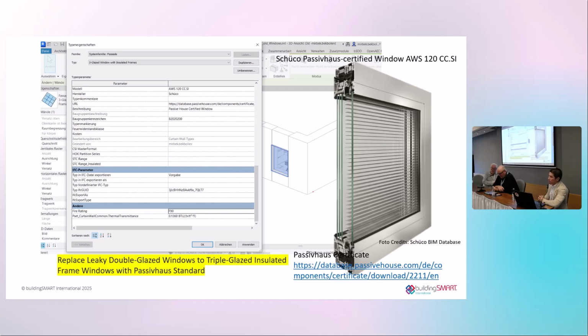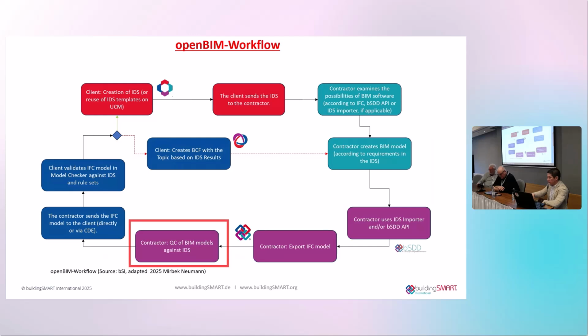So you have the manufacturer. We use exactly a real project window that actually came to our case for that climate. We checked the Passive House database for certified passive house windows and curtain walls related to that area, plus that allows us to integrate louvers or jalousie. So as you can see, it also has a certificate that we simply added in the BIM model, and of course it will be a part of the IFC model directly. So we run QA, quality assurance. We run again